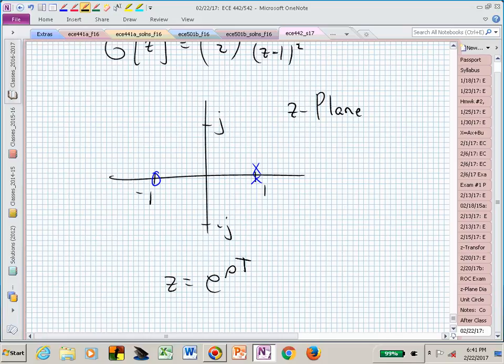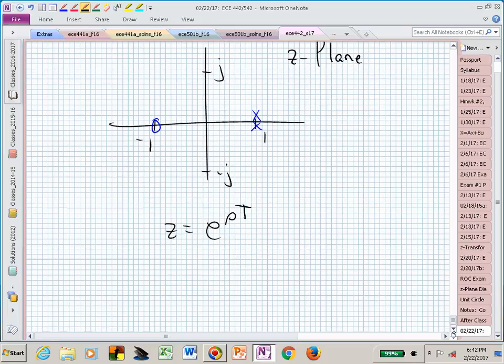Now we have a pure mass. We have 2 poles right at 1. Where's that relative to the stability boundary? Where's our stability boundary in the z-plane? The unit circle, right? It's right on the boundary, just like our double integrator. It's right on the stability boundary in the s-plane. All right. Well, that was sort of a big step. We went from crawling again to maybe jogging with this pure mass. Let's take it back a step.